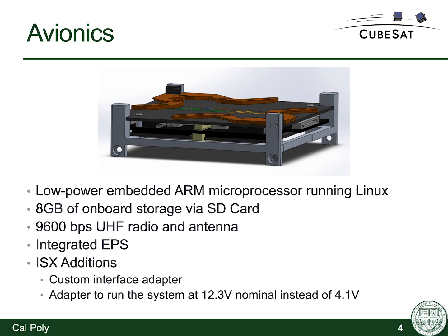In addition, we had to make a few customizations for ISX. There's a custom interface adapter that connects to the avionics board and then provides the correct breakout and electrical connections for the ISX payload. We also had to add an adapter to run the system at sort of 12.3 volt nominal instead of our standard 4.1.